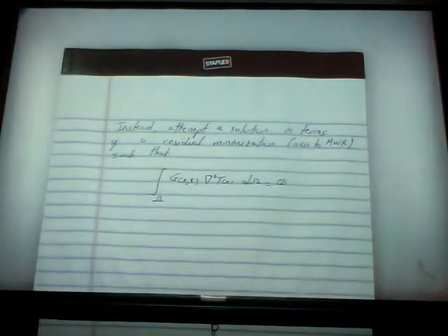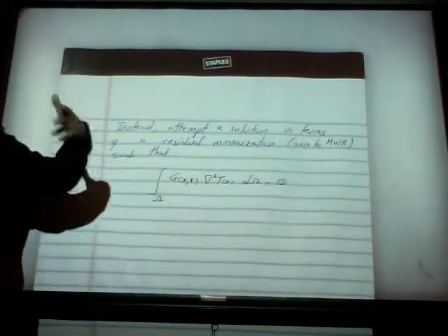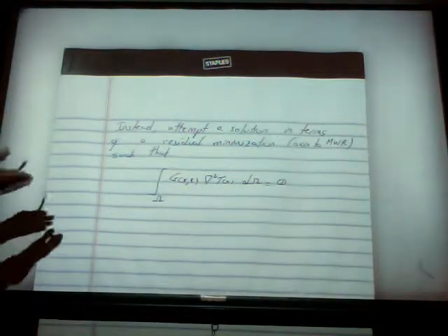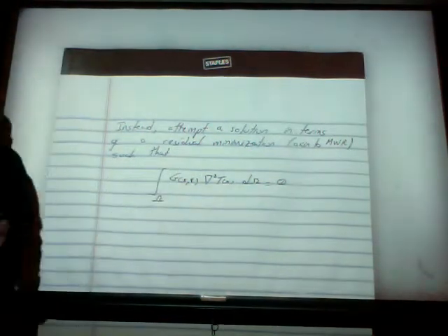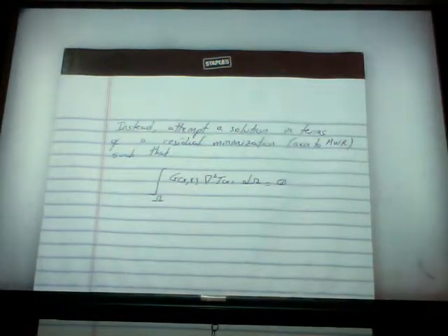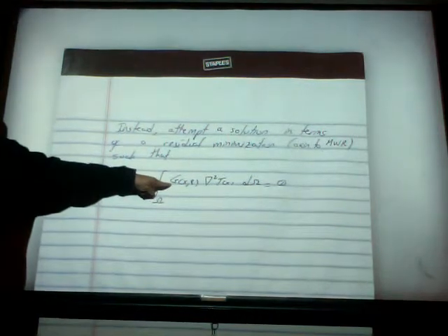All right? So, what's that thing? It's akin to the method of weighted residuals. Because remember what we did in the method of weighted residuals? We took the equation, we multiplied times the weight function, we integrated and made that equal to 0. That's the residual minimization. So this g is effectively a weight function. We just don't know what it is yet. In the method of weighted residuals, if we make g equal to the Dirac delta function, that's called collocation.